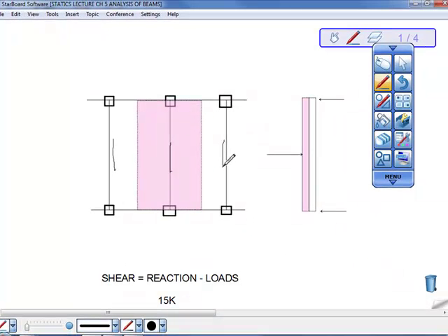And when you calculate your moments and things like that, sometimes you turn that into, just for your calculation purposes, that was 10 feet long, and that's 100 pounds per foot. That would be 10 times 100 pounds, and about in the middle. So everybody get that? Distributed loads? Distributed loads can be uneven sometimes, but more usually they are even. Is there any questions on that? Nope. Okay.